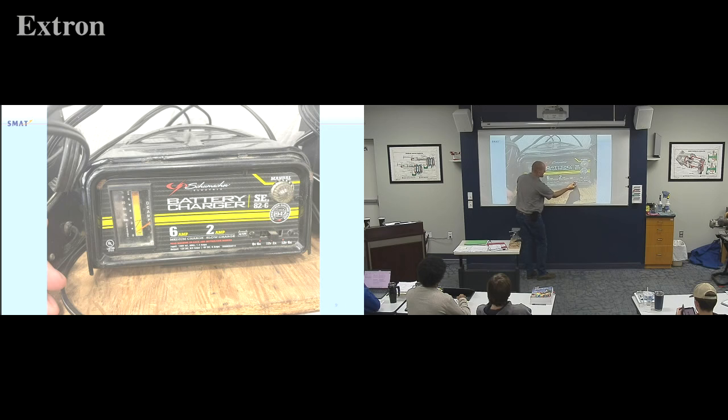So it's going to say, I'm going to hold the voltage at 6 volts, so that's constant voltage. It's actually going to be probably 7.2 or something, just above it. And it's going to say, I'm also going to hold the amperage so it doesn't go above 6 amps. It's not holding it so it doesn't go below, but it's saying I'm not going to let it go above 6 amps. If I get rid of our 6 volt one and go over to these two settings, I've got 12 volts, 2 amps, and I've got 12 volts, 6 amps.